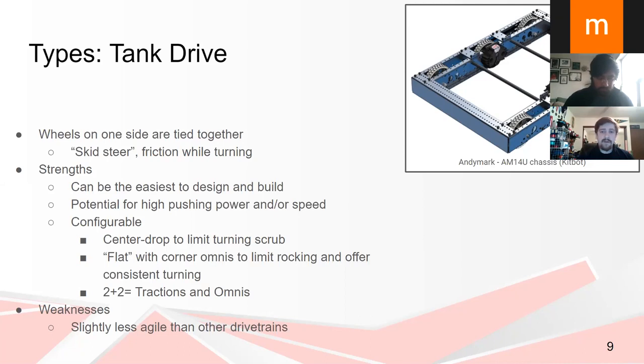The kit apart drivetrain is just a tank drive, and a lot of the time these can be done in a day, maybe 2 if you're doing completely custom, a week. They're very simple, very easy to do. Most common and successful type of drivetrain, I would say, in FRC in general.